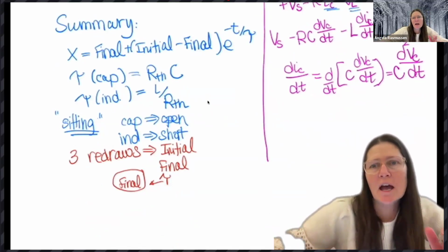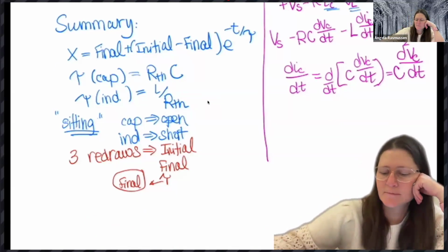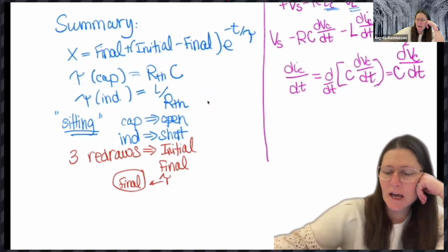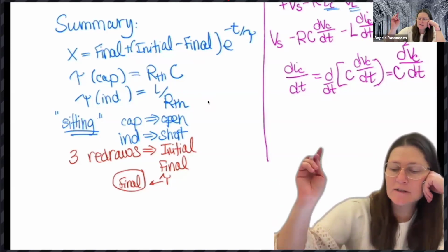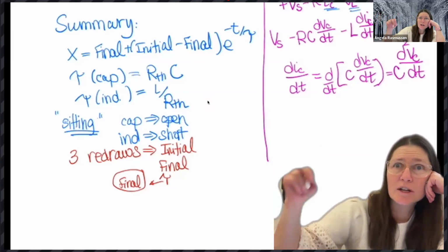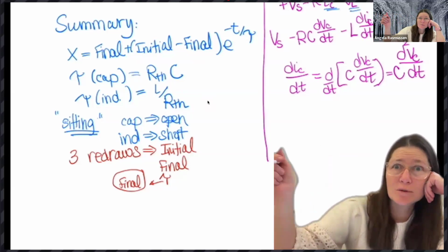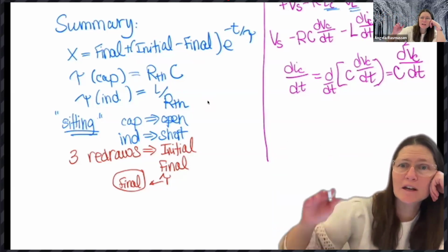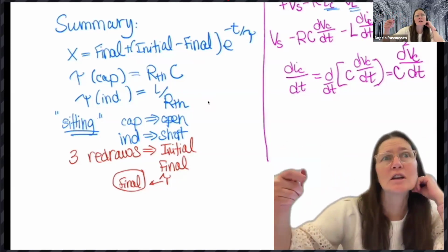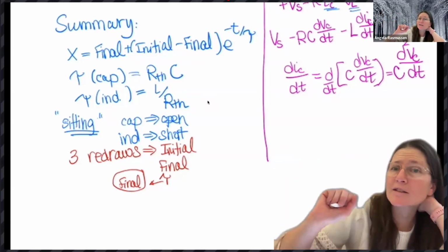And so now we have the variables all in terms of VC. What I did here was look at the equation: VC and IC are two unknowns. Is there a way to get to just one unknown? I have IC in terms of VC, so if I differentiate it, I can plug that in for that L dIC/dt.